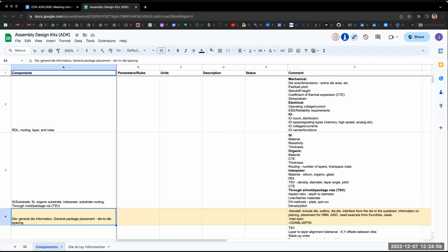Well, right now we're talking about assembly rules, right? So these are the interconnect rules. And there's going to be several categories, right? We've got interposer, we've got organic interposer, fan out, whatever you want to call it, and you have a traditional substrate, right? I think probably the easiest one to start with is the silicon interposer, because they're all relatively straightforward. And then we need to figure out the rest. I think fan out would be good, and BGA. Those are the three main ones that we need to cover, and we want to make sure we have a common format that can describe all of those.